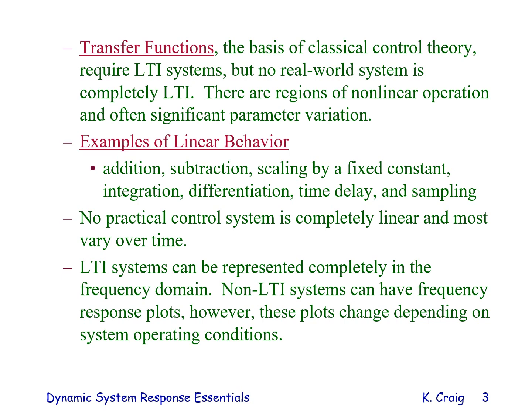Transfer functions, the basis of classical control theory, require LTI systems, but no real-world system is completely LTI. There are regions of nonlinear operation and often significant parameter variation. Examples of linear behavior include addition, subtraction, scaling by a fixed constant, integration, differentiation, time delay, and sampling. No practical control system is completely linear, and most vary over time.